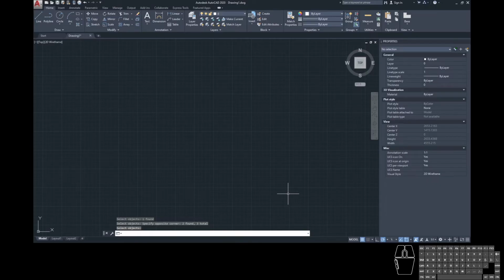To undo something that you've done in AutoCAD, you can Control Z, like with most programs. You've also got the option of using the arrows up the top here to click forward and backwards and look at all of your previous options to redo or undo. The other option we have to engage the erase tool is, of course, to type the word erase. That then gives us the option to engage erase with the enter button, and you can tell that we have done so because it's giving us erase and it's telling us to select objects. The other option we have is to use the shortcut for erase, which is E, enter. Again, it's telling us to select the objects, and we can hit enter to finalize the erase.